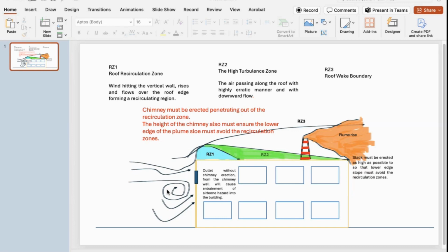The flow rate at the chimney comes right after the fan. It can always be taken as a performance index because it churns out the actual volume of air right after going through every single restriction. So a good design of chimney is important. The performance monitoring by taking the flow rate is important. It also can be used to gauge the overall performance of the system.